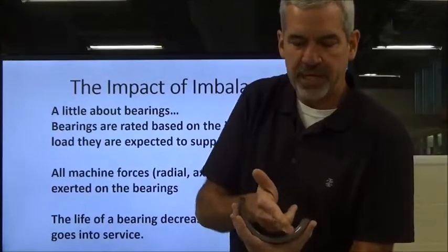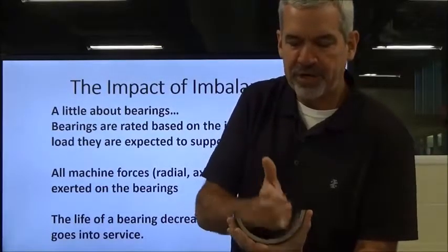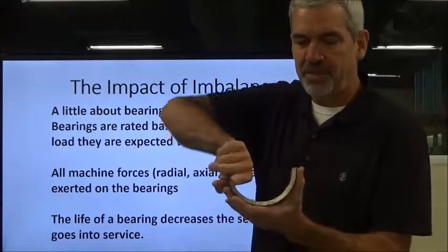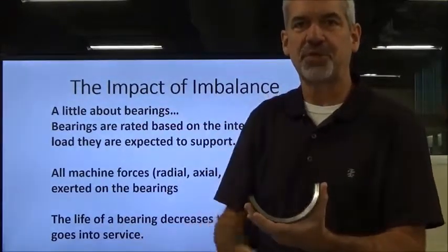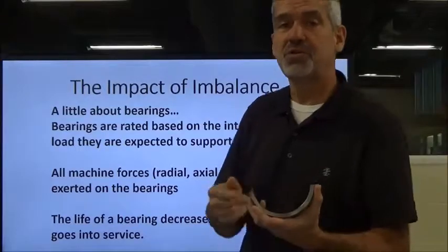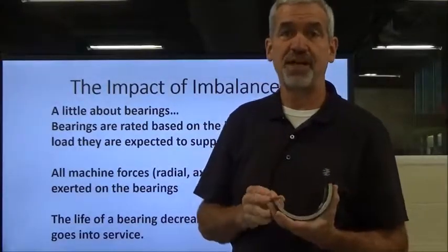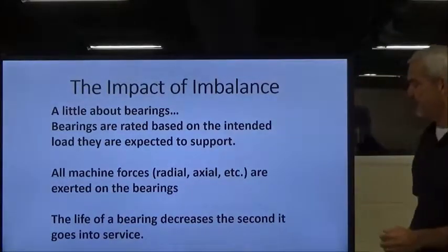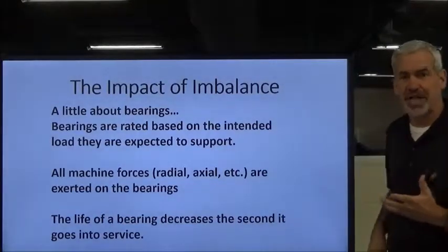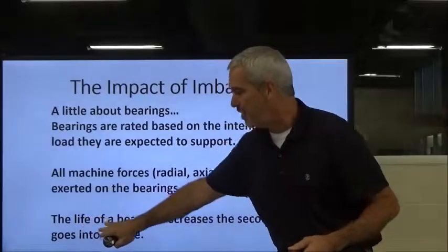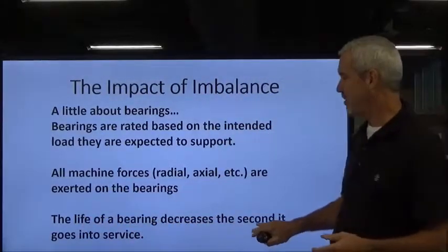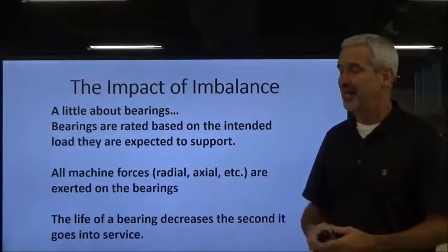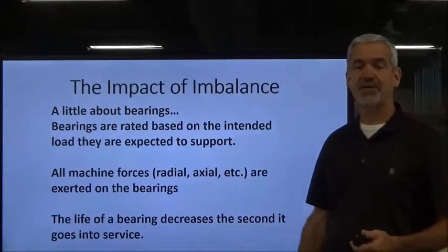And the rolling elements were sitting there hammering little divots into the outer race, so that when we fired it up, those balls fell into those divots and were creating a vibration signal, and it was so severe that it looked like the bearing was defective. It was indeed defective, but it had no life on it whatsoever. It had 0 runtime on it. So that is my one experience where I can dispute this statement that the life of a bearing decreases the second it goes into service, the second you turn that machine on. Actually, it can go into failure before then.